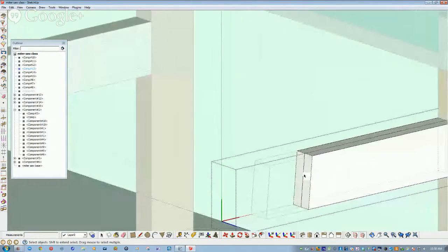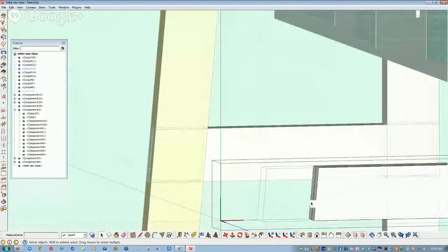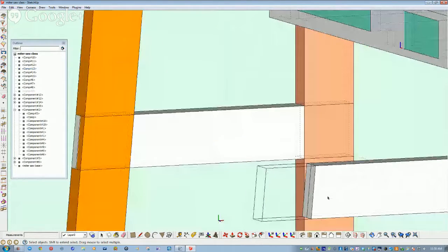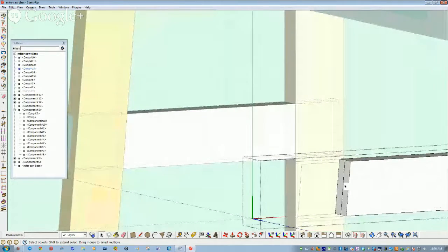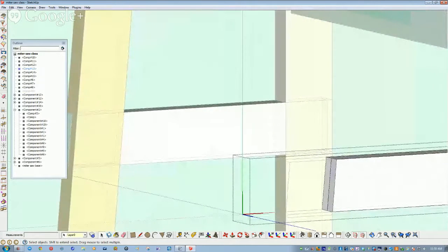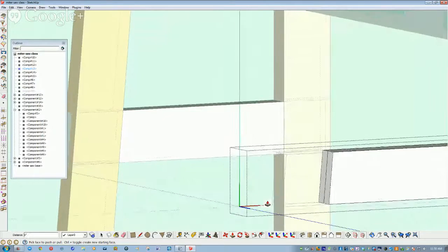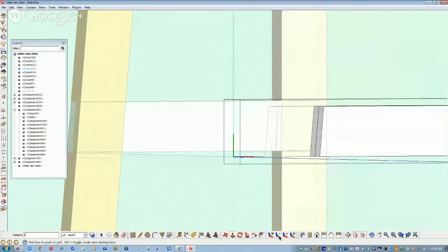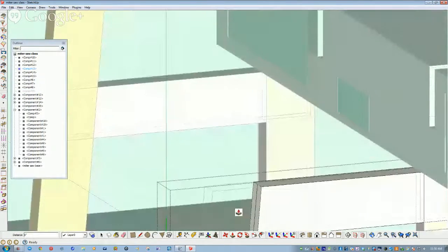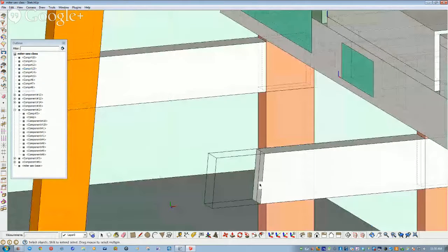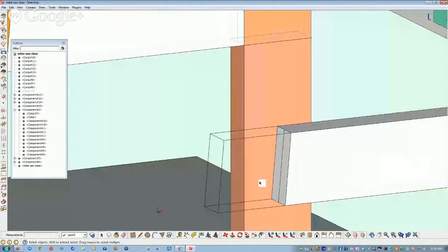Now, first I'll show you what happens if you're working from an angled face and you want to extrude it out. You go into pull and it goes out at the angle it's on. It always goes perpendicular to the face. There are ways to work around it with these 4 icons down here. That's not part of this lesson, so I'm not going to worry about it.